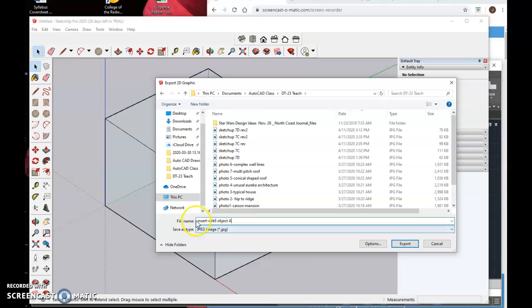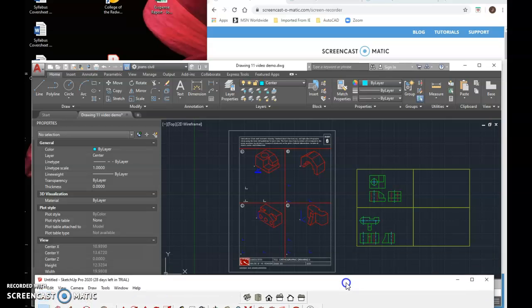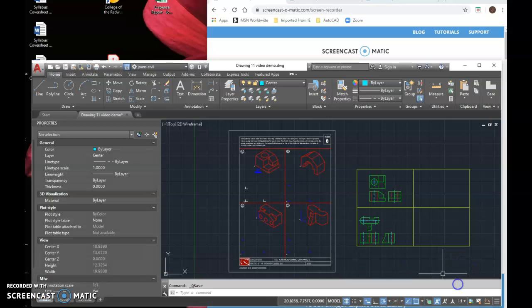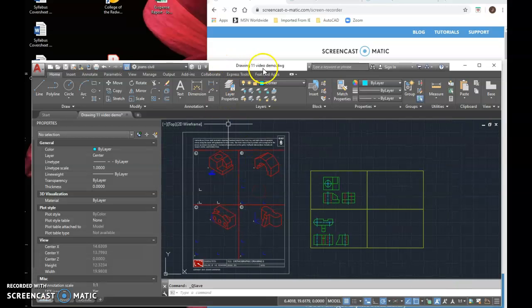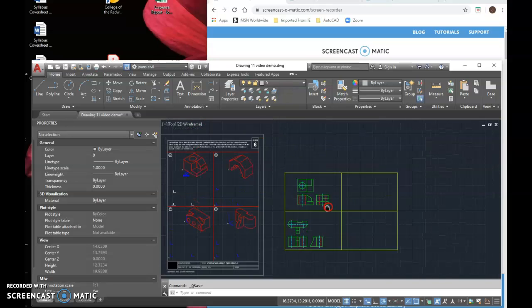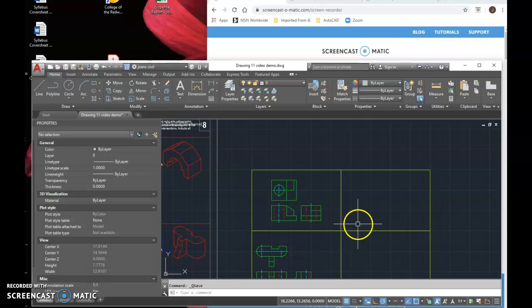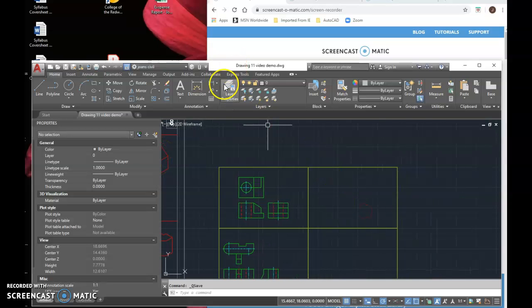Get a lot of these things going. You got to make sure you got them labeled somewhere you can determine what they are. Otherwise, you'll be opening them to look at them. And that should be done. So then we can just go back over to here. And we're going to insert that on layer 0, because that's what we like to do with inserted objects. And that's object A. We've already centered it. So I'm going to put the graphic over there.